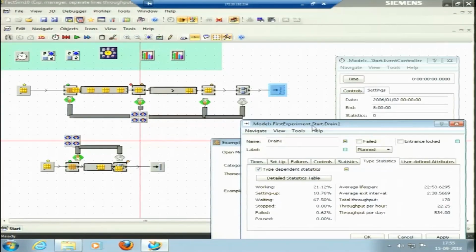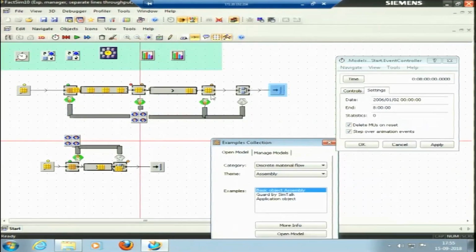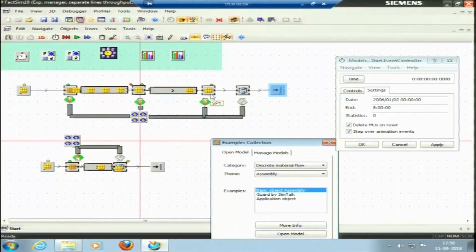This is based upon the input that we have given to the specific processes, which I will discuss. It is the setup time, processing time, and the availability, whether it is available for the complete time, or for 95% or 90% of the time. Then we have the distribution. For a manual process where we do not have much data, only 2-3 data points, we can pick maybe a triangular distribution. If it is an automated process, I can pick a normal distribution with very little variation because the process is automated. Based upon the inputs that we give, the software will simulate and give us a throughput.